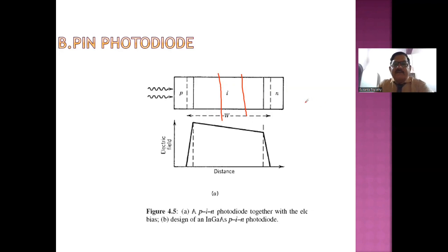Now let us say these electrons and holes are produced in this active region, they will only flow for a short distance along this N region. Therefore, there is less probability for absorption. That means whatever number of electrons you have produced in the active region, almost the same number of electrons will reach the other end of this PN junction.